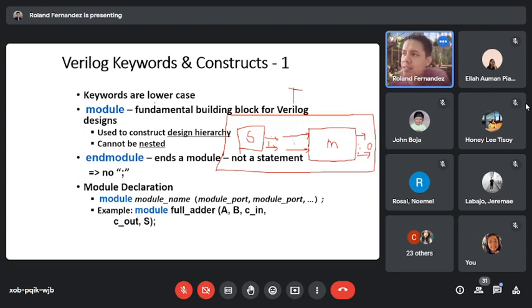Okay? So take note the module cannot be nested. You cannot put another module inside a module. The modules should end first before you create another module. Your one program can have many modules inside. That is how the construct in Verilog works; it has no construct to reuse the codes that were previously created. Your modules can all be listed one after another.